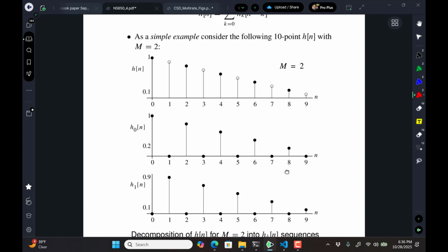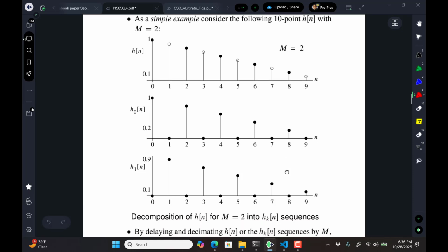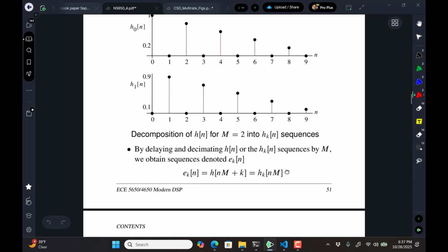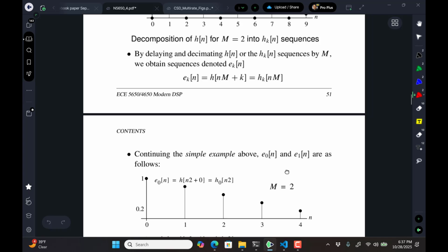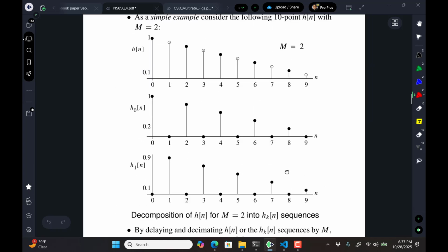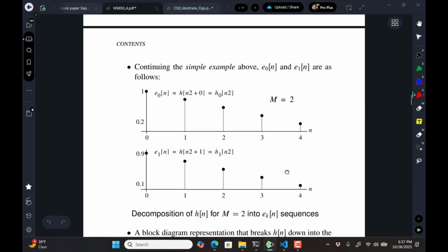If we have to decimate by more, we would break it up into more than 2 filters, but here we're decimating by 2, so we have 2 subfilters. So we have the 2 shorter filters. This is the initial block diagram, the concept block diagram for the polyphase decomposition.